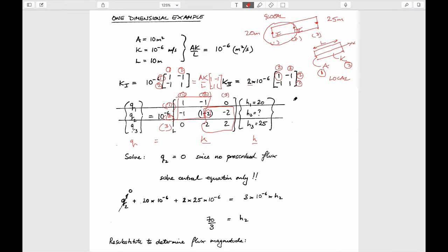And so if you understand exactly what's been done here, that is really the essence of all codes. You never, of course, see it if you're using COMSOL, but if you're developing your own codes or portions to interface with it, you certainly need to know about what those referencing conditions are, indexing conditions. So we can put together a system of equations which relate fluxes and heads through this equation we can always define, and we can always put together in a global sense.